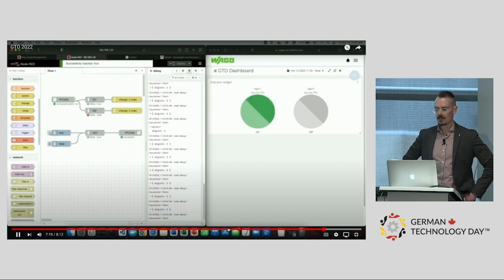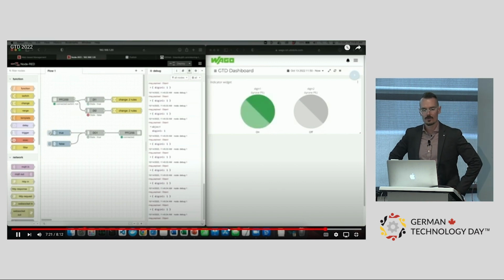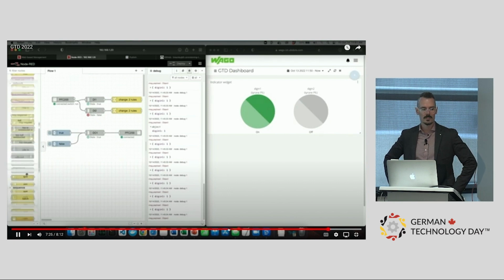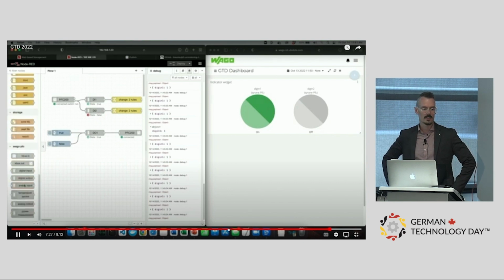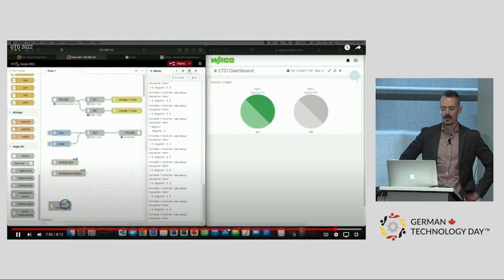You could take analog values. We've got a 3-phase power measurement module you could add in there, and you could dashboard that or set condition-based monitoring in the cloud. So if your voltage spikes or is out of tolerance, you could set it to send an alarm to somebody. There are a lot of things you can do inside of UbiDots that we haven't really talked about.